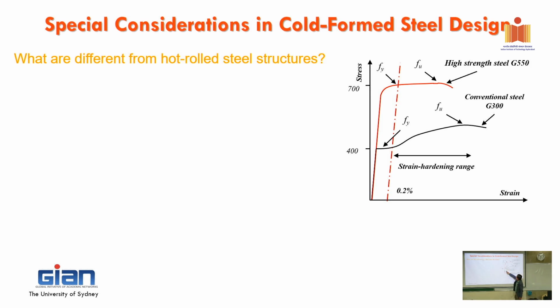Opposed to that, with high strength steel, the change in the micro scale, in all the grains and all the particles of the steel, makes the steel stronger. However, it will be less ductile. So instead of going up and then starting to be nonlinear at a clear yield point, it just gradually goes up, about 10% maybe, and it depends on the grade.